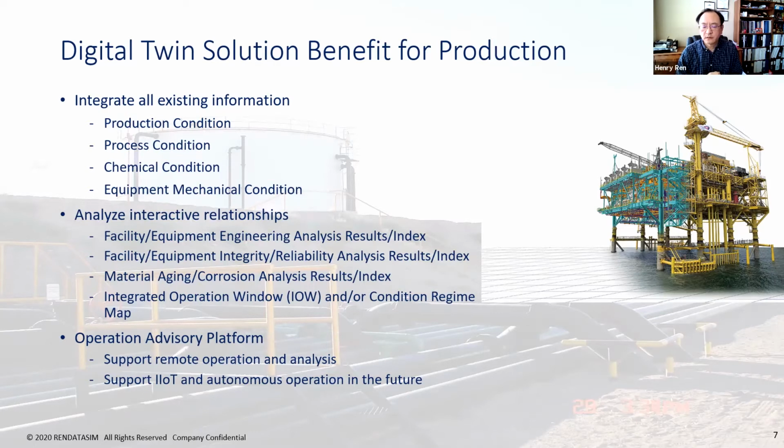FIV means fluid-induced vibration. We can quantify those behaviors and turn them into an index to guide the operation. Another thing is a material aging index, corrosion index, and it also allows us to build a more comprehensive integrated operation window and condition regime map to guide the operations.